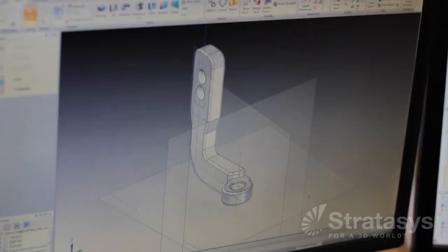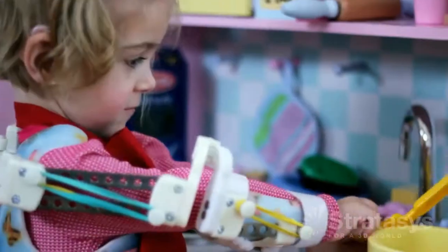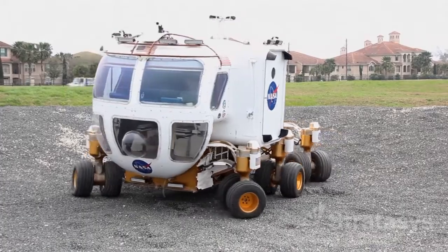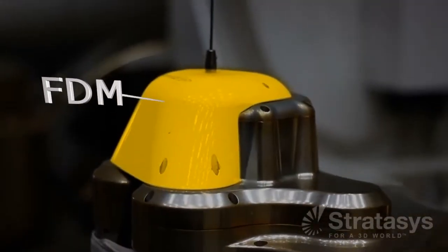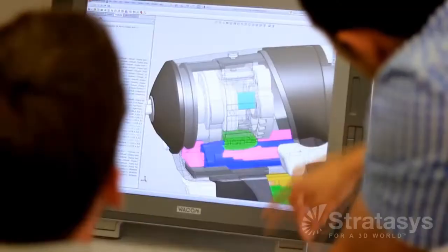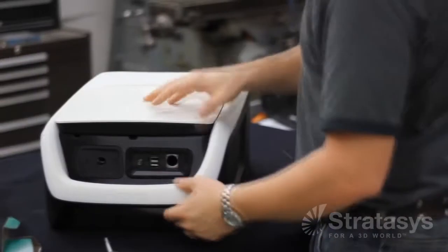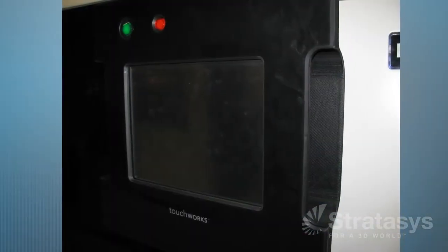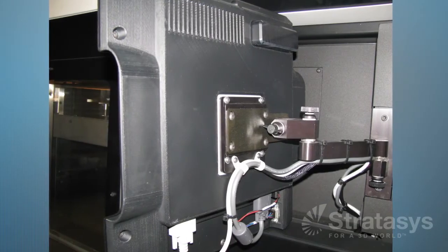So what qualifies a part as a good candidate for FDM end use? 1. The design is expected to change frequently. 2. The part is a one-off. Look for the customized product or the solutions-based products that are encountered in motorsports and processing equipment, for example. 3. Production costs can be decreased by consolidating parts so that there are less components to assemble and manufacture. 4. The product demands or deserves a design that is impossible or impractical to manufacture with traditional methods.